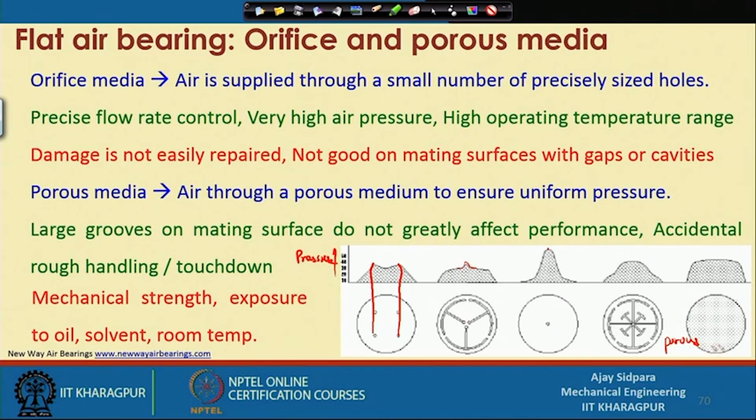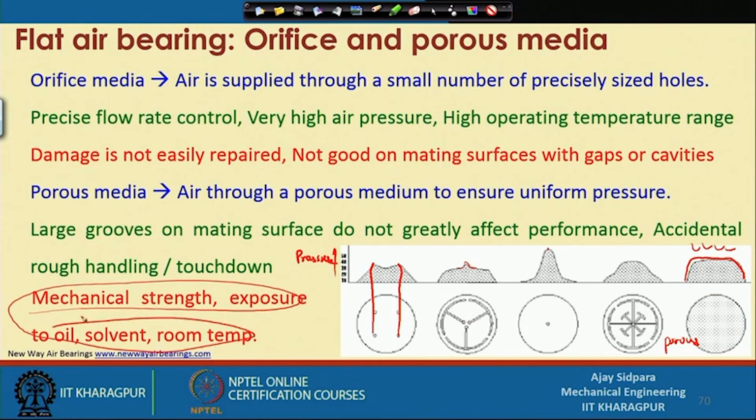Right. In porous media we know that holes are throughout because of the porosity, and you can see how uniform the pressure profile is. This is what is required, because you do not want a non-uniform pressure profile on a workpiece surface. That way the loading is uniform, and when the loading is uniform you may not encounter some type of deformation or some type of alignment problems. So, this is one of the good things, but it is still limited by many things. So, it is up to the application engineer which one is good for that particular application.